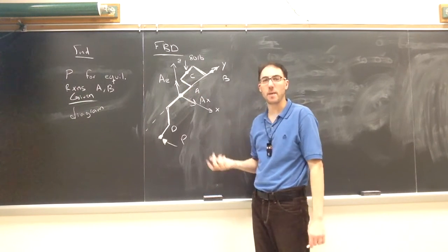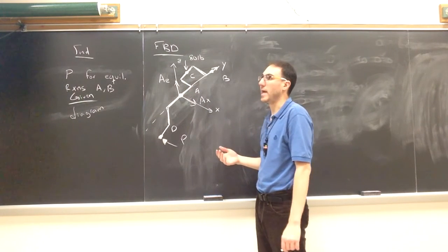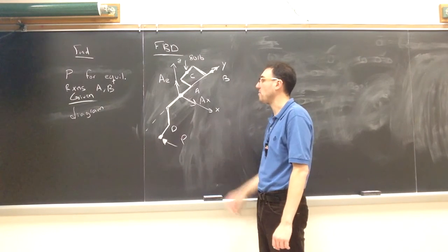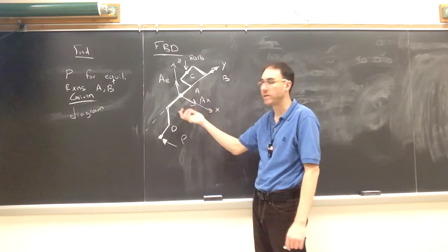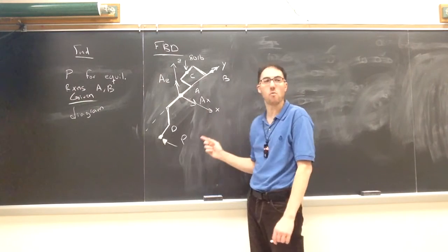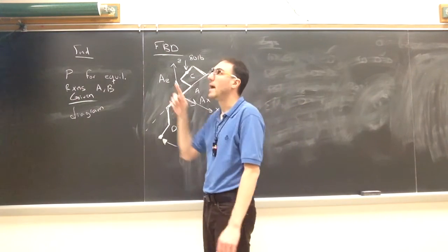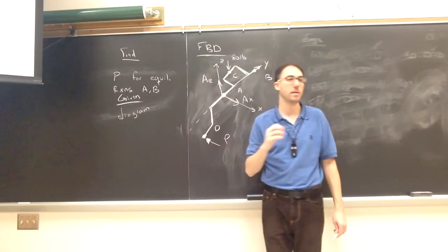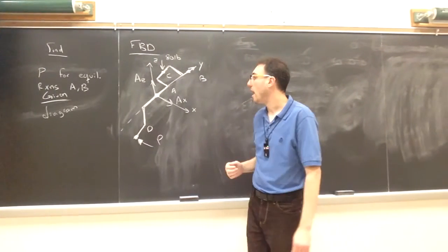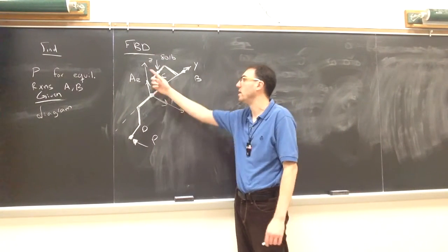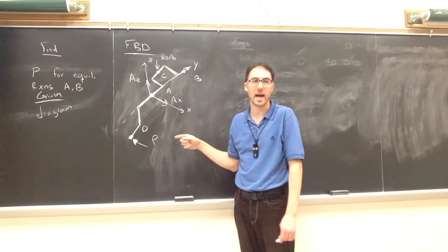And then we have to think about rotations. This is a round shaft and a round bearing, so it can freely rotate around the y-axis. Then the information about proper alignment comes in: do we include moments around the z-axis or the x-axis?